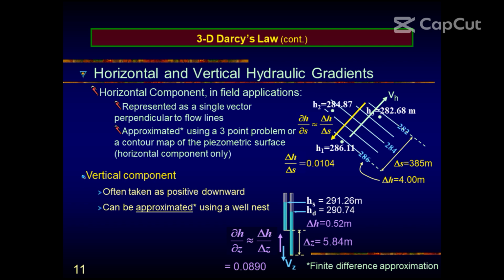It's just like when you have, let's say, this is your ground surface, and then you sink your wells, observation wells, or test wells, and the pressure head here is the same as the pressure head here. So you can have some lines, depending on the piezometers. By piezometers, we mean test wells that penetrate the aquifer to give the level of the water table, the piezometric head, or the phreatic surface.